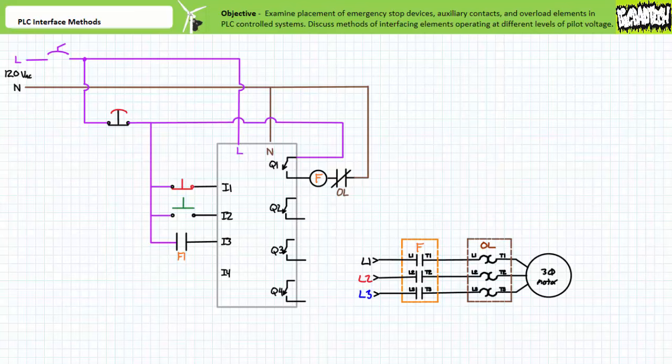that change states when the coil is energized and the contact carrier is pulled in. This accessory input is essentially feedback to the PLC, verifying the F contactor has pulled in and the motor is in fact energized. If all goes well, the PLC should energize the output and very quickly receive confirmation that the F contactor has closed. If, however, during the course of operation, an overload occurs, the overload element directly de-energizes the